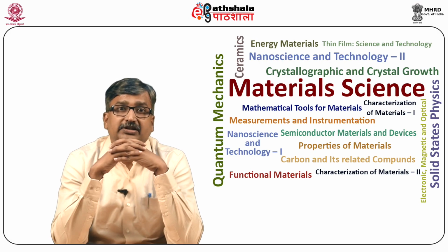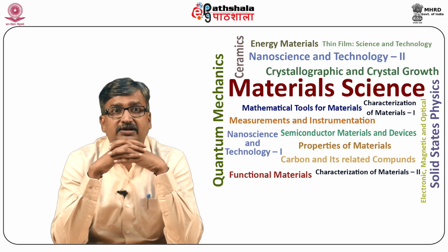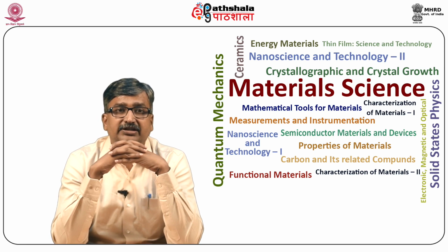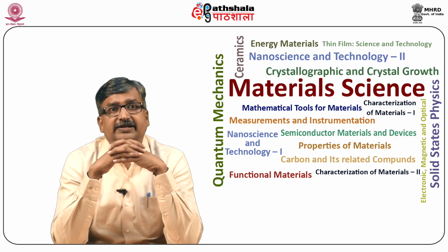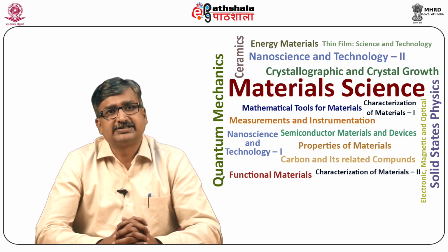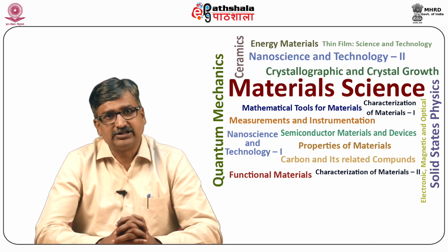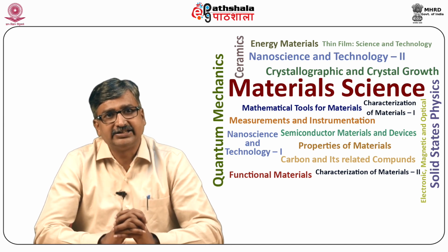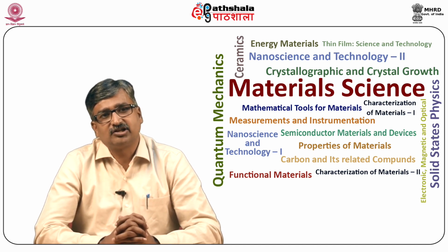So student, let us now summarize what we have learned in this module. We learned that wettability is the tendency of one fluid to spread or adhere to a solid surface in the presence of another immiscible fluid. Wetting of the surface depends strongly upon the contact angle theta between the liquid and solid.